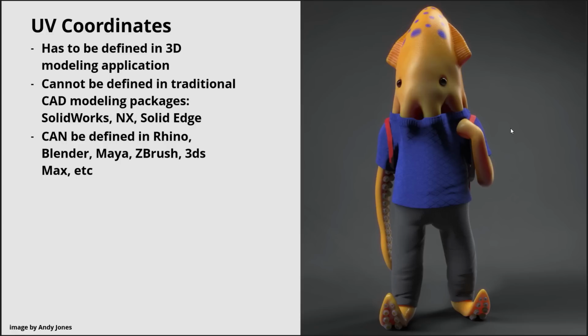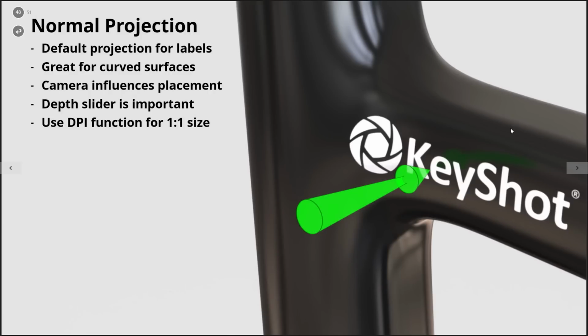Again, most CAD packages, I hate to say it, but you're out of luck. In that case, we'd use some procedural textures and try to get around it. But if you are using something like Rhino, then take a look at UV unwrapping and assignment, because that will give you a lot of control over how your textures are wrapping around surfaces.